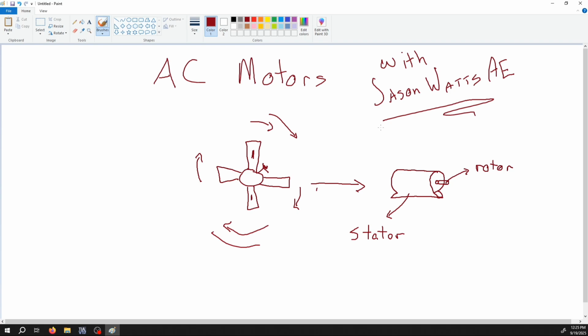The thing about this industrial motor is the voltages, depending on where you are, can vary between 360 volts all the way up to 590 in some cases. And this is three-phase instead of single phase. The frequency will still be the same. In the US, it'll be 60 hertz. In other countries, it will probably be 50 hertz. And that honestly is the most important thing that we need to correlate between these.